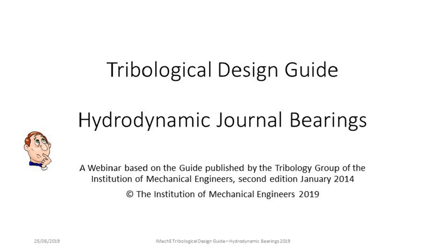Okay, and then the final 2 questions. One of them says, what are the contributors in heat generation in bearing or heat added to oil in hydrodynamic bearings? Well, essentially, it's the shear rate in the oil. If you know what the viscosity of the oil is, and you know the dimensions of the bearing, and you know the shear rate, and so on, then you can work out the power being absorbed by the bearing.